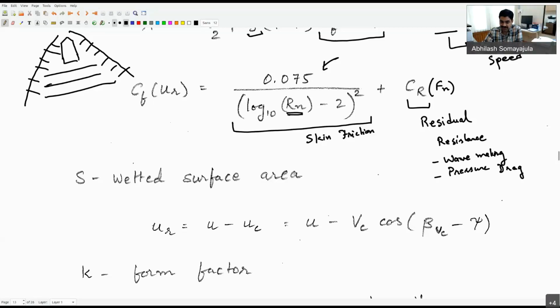You can see that a portion of this mathematics combines with that portion of the mathematics as well, especially when I'm looking at zero frequency. Because when I'm talking about zero frequency, I'm really moving the ship very, very slowly. So what is the radiation damping observed at that time is what I'm talking about. And as long as my ship doesn't have a forward speed, those values should typically be zero.